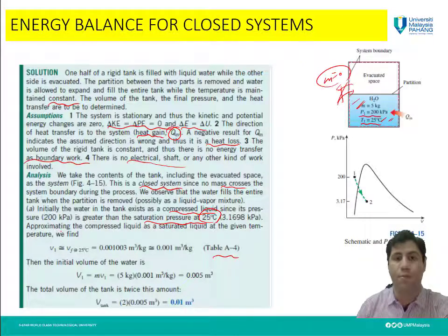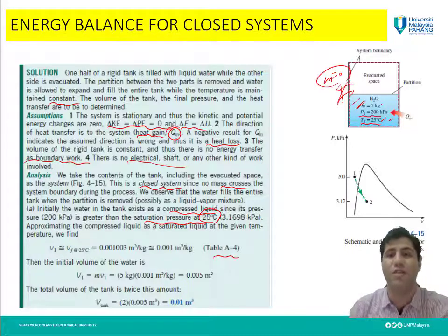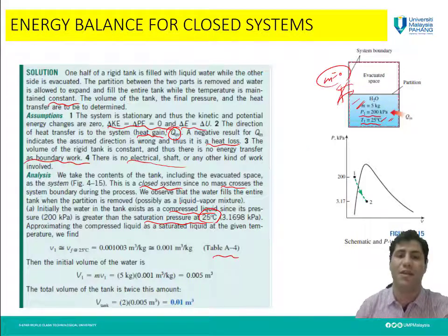We have compressed liquid in this state. So we can approximate, and by approximation we can use the properties of saturated liquid for water. If you remember, we had this assumption: when we have a compressed liquid, we can use the properties of saturated liquid.